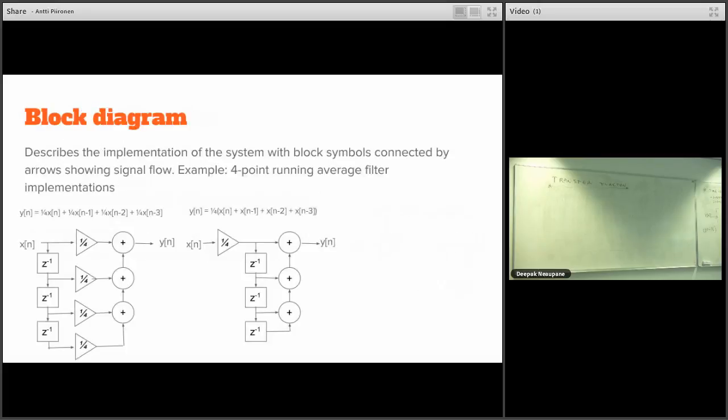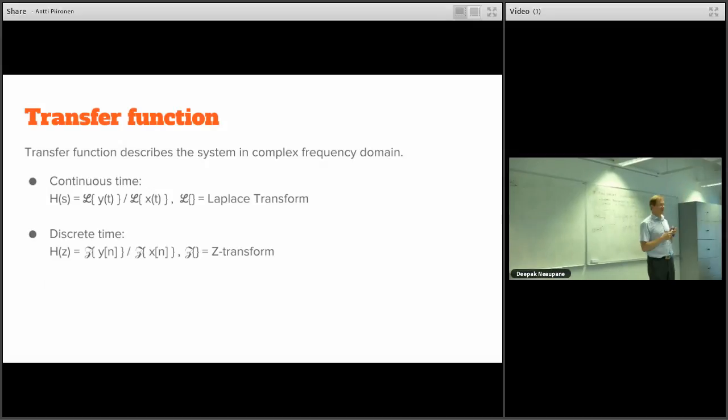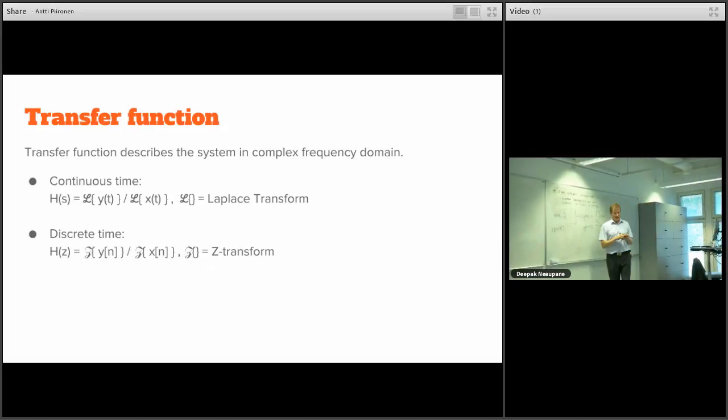Block diagrams. Basically, it's a function that describes the system in complex spectrum, and that's a little bit hard to understand. Okay. In spectral space, you can actually divide this system into a series of sinusoid functions. It's periodic, but what does it have to do with this transfer function? Basically, everything falls back into the so-called convolution theorem, where you multiply the system input in frequency space with a transfer function, and that gives you the frequency space output. Okay.